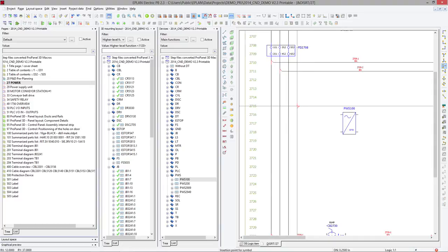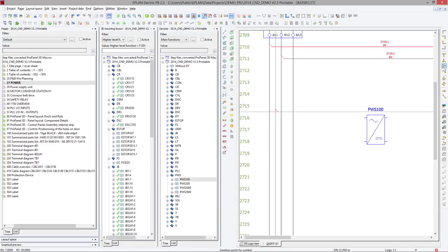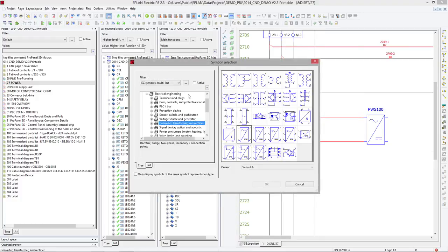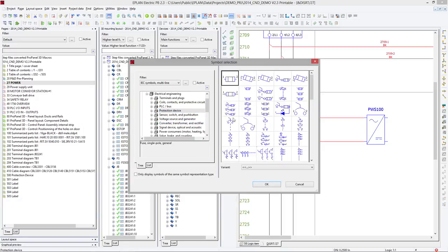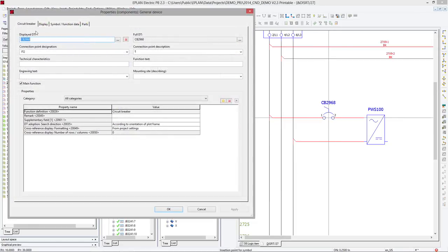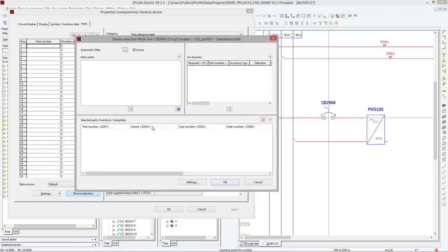This is just part of the EPLAN. Remember the T node, you reverse the T node so it actually connects to the distribution block at the top. You want to place it on L1, L2, there we go, etc. If you place a component here, so let's go and let's place a protection device, a circuit breaker. So we're going to pick here a circuit breaker. This circuit breaker will be a single circuit breaker at this point, and I'm going to use a part number.